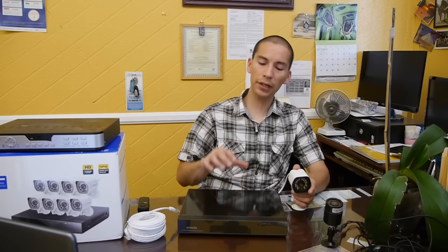You can't use a DVR you already own because that's specifically for your cable TV, but there are plenty of standalone DVRs made specifically for security cameras. The main thing you want to look for in a DVR is how many channels they can record. Each camera feed is one channel, so a 4-camera system would require a 4-channel DVR, and an 8-camera system would require an 8-channel DVR, and so forth.